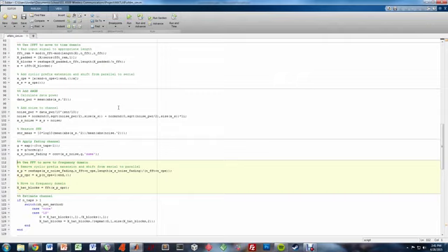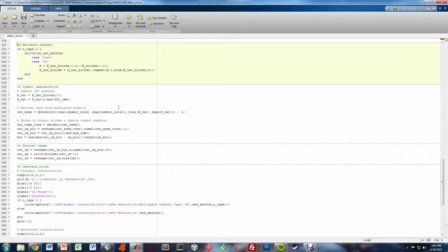Here, the cyclic prefix extension is removed, and the data is shifted from serial to parallel. The fast Fourier transform is then used to move the data from the time domain to the frequency domain. Here we apply channel estimation, in this case least squares. The data is then recovered from the modulated symbols and parsed back into a binary stream.